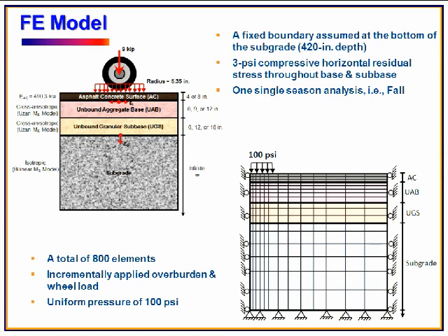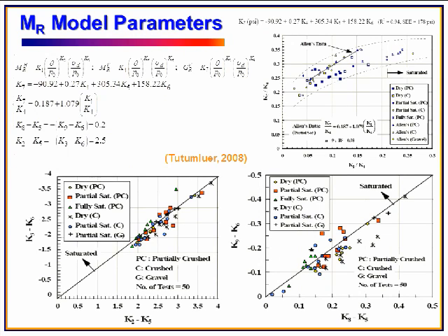So in this case, with the capability of GT-PAVE, we modeled the base and sub-base layers as stress-dependent, cross-anisotropic. The subgrade was using a bilinear model. And we just did one single seating analysis, just 4 seatings. So basically, the modulus is just for the 4 seatings, the standard 4 seatings. We didn't do a full seasonal analysis as we did previously for the MnPave program, because in their database, they didn't run resilient modulus testing for cross-anisotropy. So what we did is we used methods proposed by Professor Tutumluer and Thompson to estimate the cross-anisotropic model parameters. Here is the procedure.